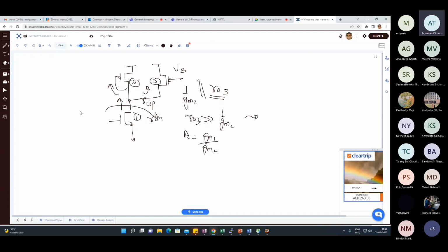The swing, I think, will be better now. Why will it be better? Like for the current source load, we had seen the upper swing, like V out max is better. What do you mean? You have this one still present, right? This is not gone. This guy is still present, right? So still you can't go higher than VDD minus mod VTP.